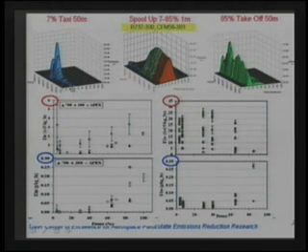So at idle, you're dominated by the gas-to-particle conversion that's occurring as the plume expands. You're dominated by that, too, at maximum power for this study, but you're also seeing the component from the engine itself, you know, the soot component. Rick will be telling you a lot more about the composition of this later, okay? And that's borne out when we look at these number-based emission index plots.